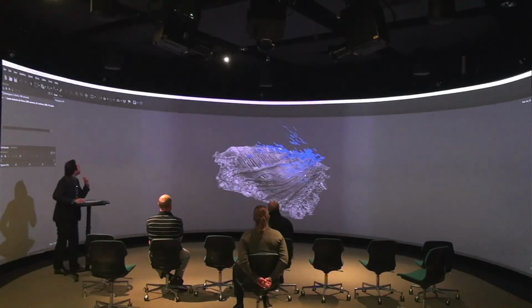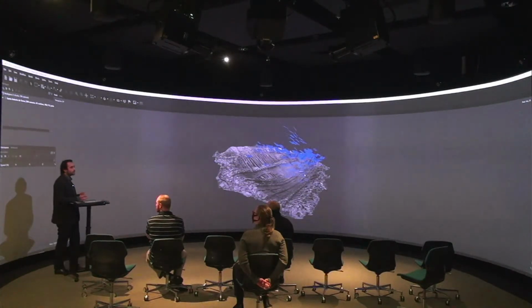Now, I don't have it in this project because it's a bit hard to navigate, but usually with Metashape, you end up having so many different chunks that you're experimenting with image sets. You try and build a reconstruction, and based on the amount of coverage you have, you place models that might align with another reconstruction, then you align those chunks and merge them, then continue until you progressively build a shipwreck. Sometimes the exposure in the images is different, and that can stop it from aligning. Sometimes they're too far apart, but I found that method of generating little jigsaw pieces to fit it all together quite useful.